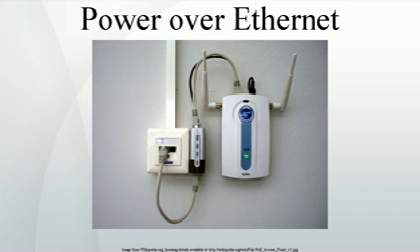Power may also be transmitted on the data conductors by applying a common mode voltage to each pair. Because Ethernet uses differential signaling, this does not interfere with data transmission. The common mode voltage is easily extracted using the center tap of the standard Ethernet pulse transformer. This is similar to the phantom power technique commonly used for powering audio microphones. In the IEEE standards, this is referred to as alternative A.